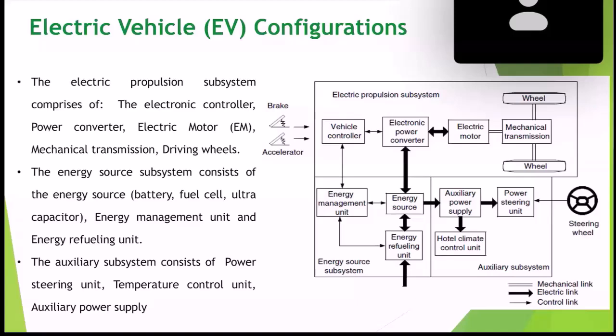In order to avoid confusion, nowadays this torque-based engine and torque-based powertrain control system has been formulated, where the cumulative torque requirement from the various systems is calculated, and according to the torque requirement, the torque is realized with the help of the designed control systems. That is the role of the vehicle controller. Depending upon the torque requirement, the vehicle controller will calculate and identify the torque required from the motor.